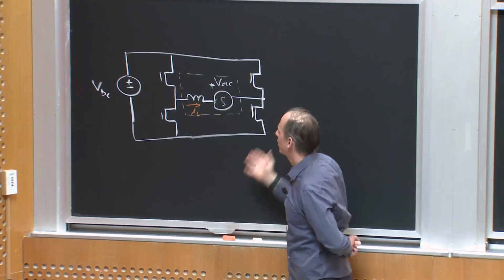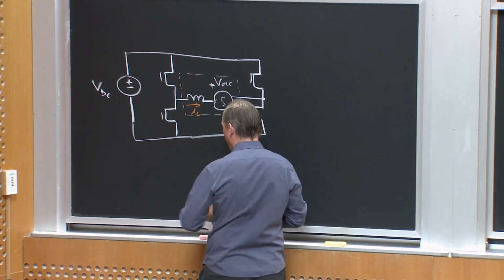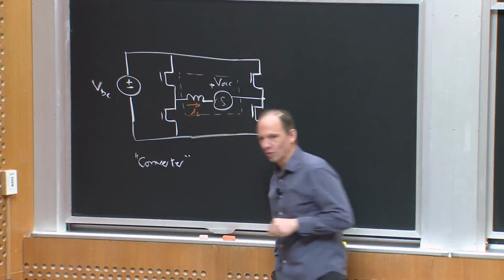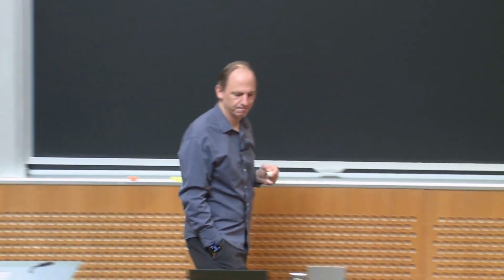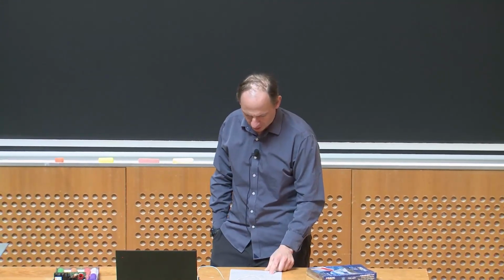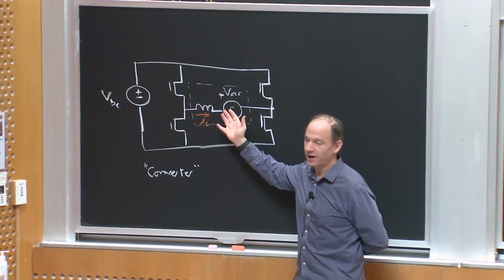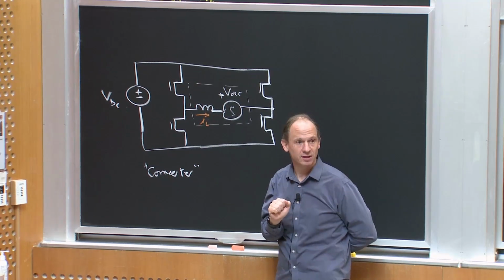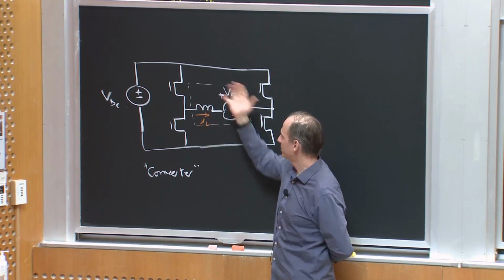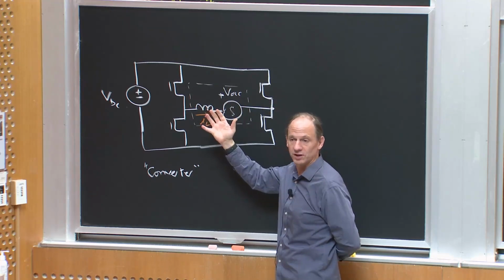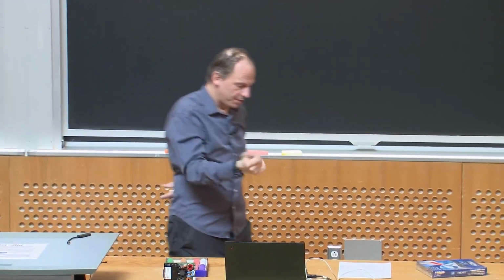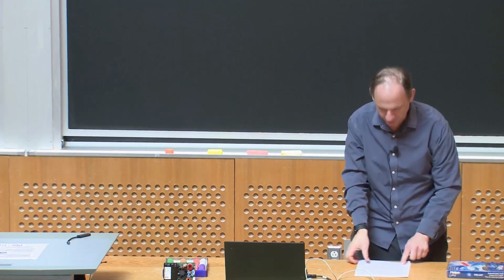So just because I often call this an inverter, we might really think of it as a converter, meaning it can be an inverter or a rectifier depending upon how I'm controlling it. And this is very common. Another place could be the AC grid. If I had a solar panel stack here and I wanted to push energy out into the AC grid, perhaps I use exactly this structure. So there's another place you might do it, and that's just many applications of an inverter.